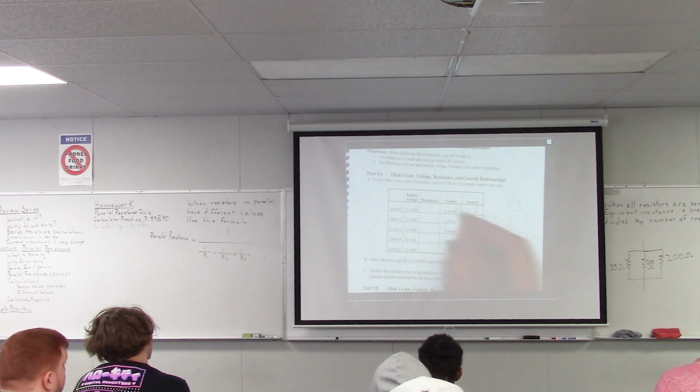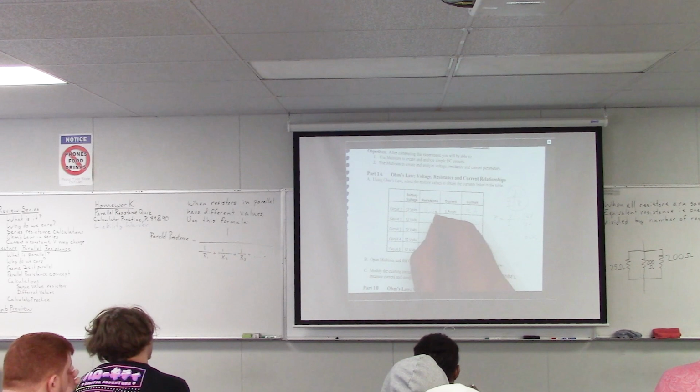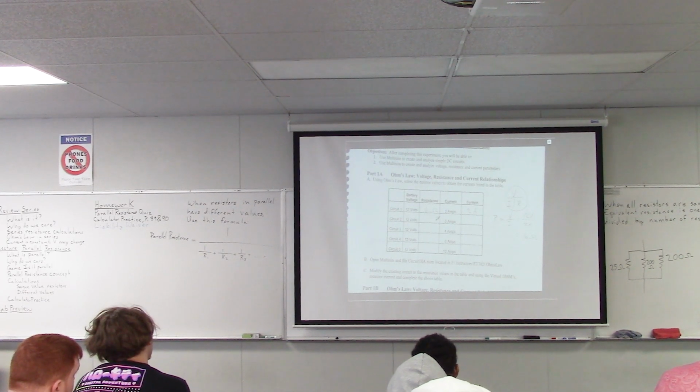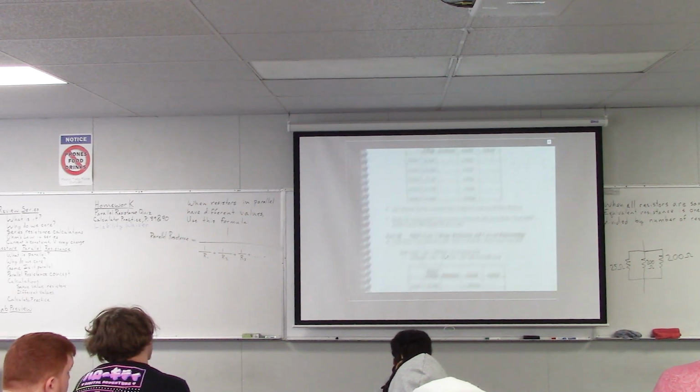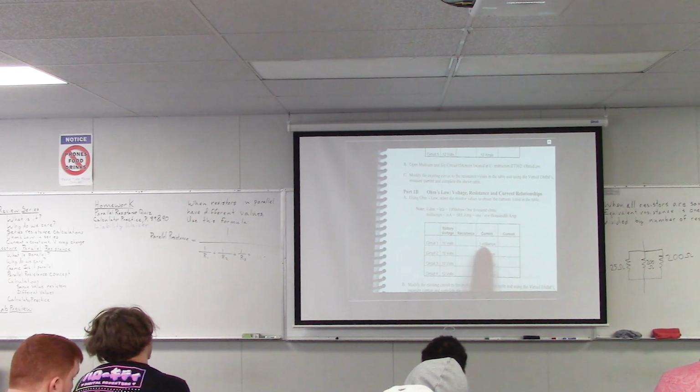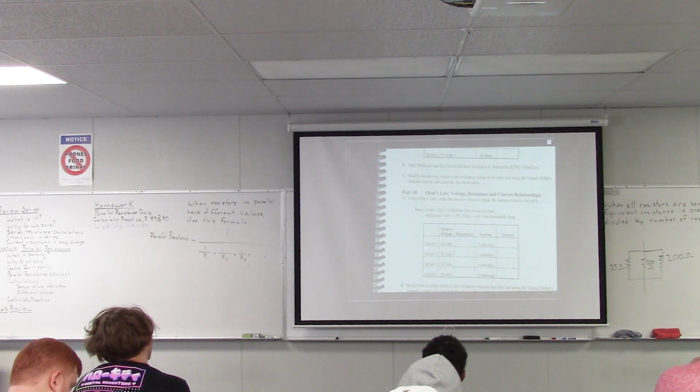So we use 6 ohms there and 2 amps. So we're all set, okay? Then you would repeat the process and pick a resistor value that would give you 3 amps, pick a resistor for 4 amps, and so on, all down there. And same thing down here: you're going to pick resistor values to give you milliamp currents.